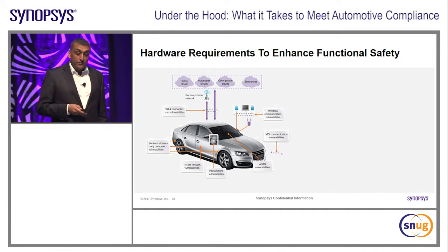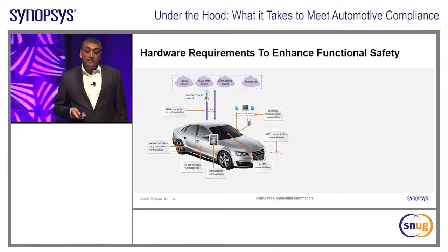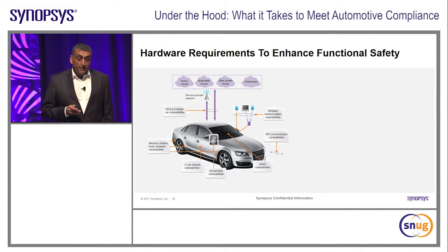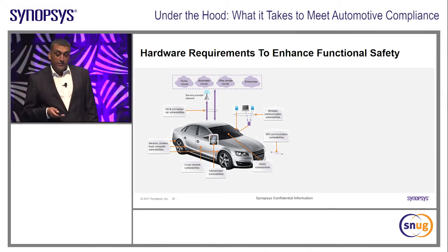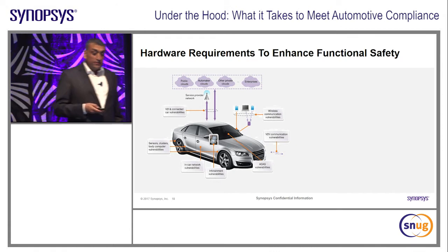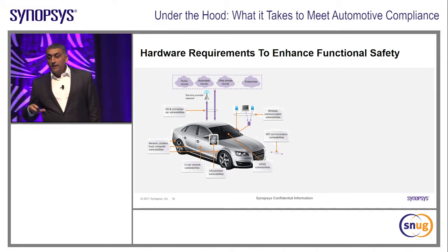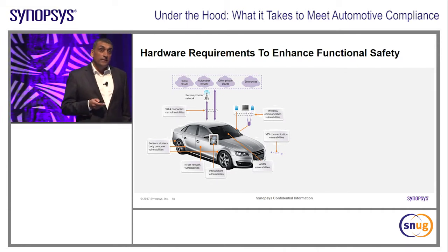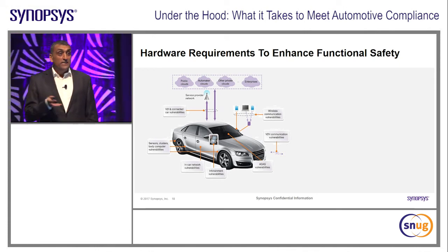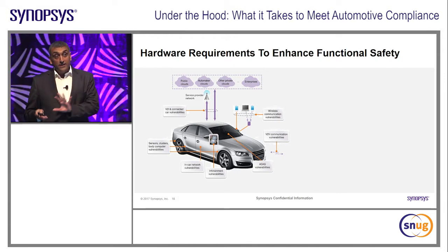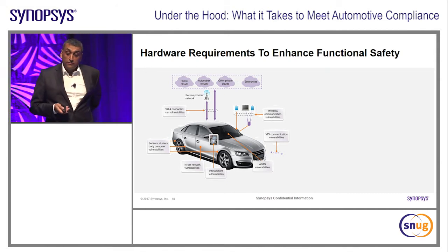In the digital IP blocks, you can add write protection to your elastic store. You can add parity protection to your data path, protection for your read-write memories. You can have dedicated interrupts, parity check on state registers, and you add redundancy for error handling and the elastic buffers. And I'll go into a bit more detail in terms of redundancy and how redundancy impacts your ASIL level. So the example I'm going to give later on is a microprocessor where we're meeting ASIL D, the highest requirements for functional safety, but we're adding so much redundancy in order to do that that we've got to include safety monitors in order to meet that.